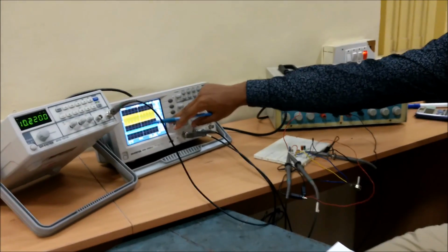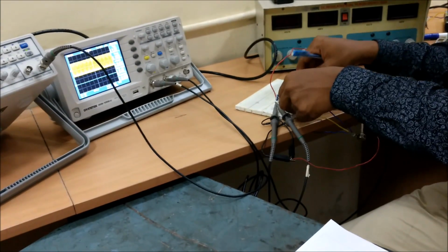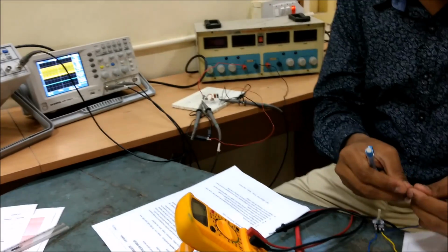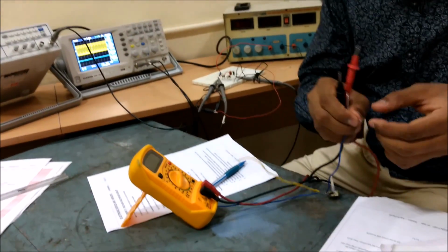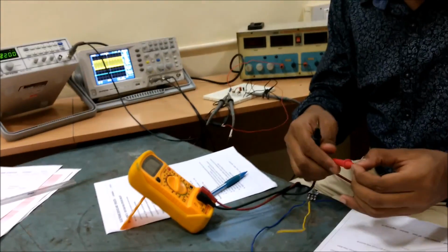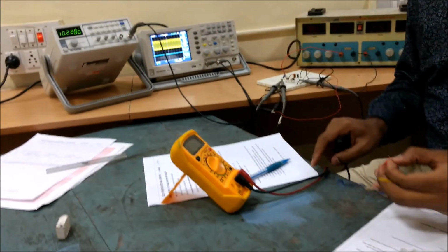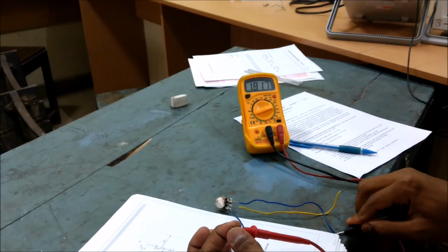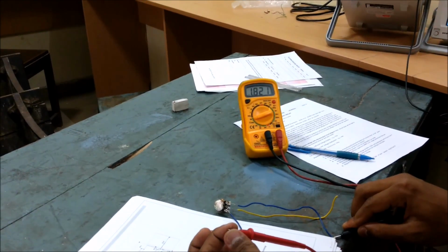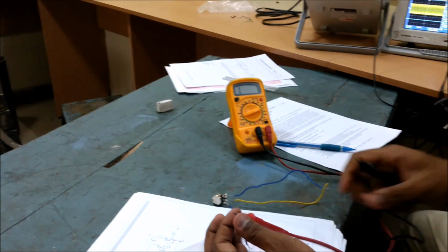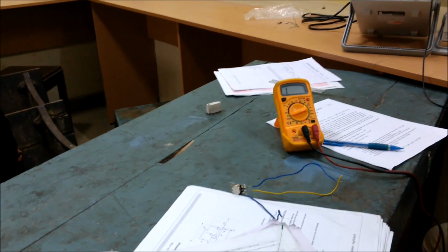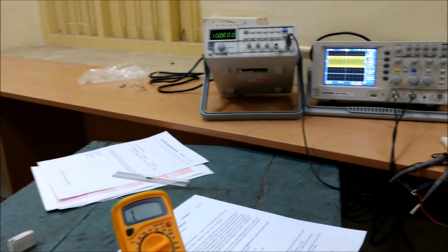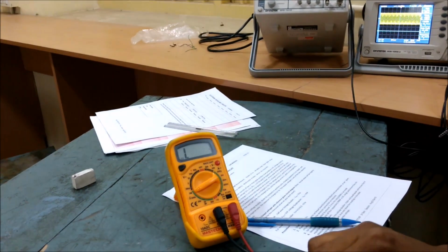Connected the pot and the output exactly reduces to half. Now we will calculate. The input resistance is in series with 330 kilo ohm. Now let's see what the input impedance is, the total resistance. Guys, we can see that it's almost 1.8 mega ohm. This is our input impedance with bootstrapping. Without bootstrapping, we've seen it's around 700 to 800 kilo ohms. Now with bootstrap, it's around 1.8 mega ohm, right?